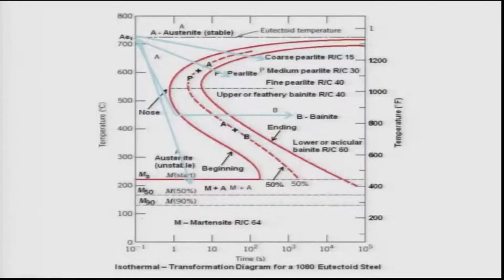If we quench to an oil at a temperature of 150 degrees Celsius, then it will lead to 50% to 60% martensite. And once it is quenched below 100 degrees Celsius, suppose at room temperature, 30 degrees Celsius, then almost 97% to 98% martensite will form.